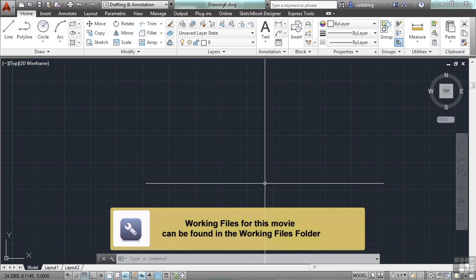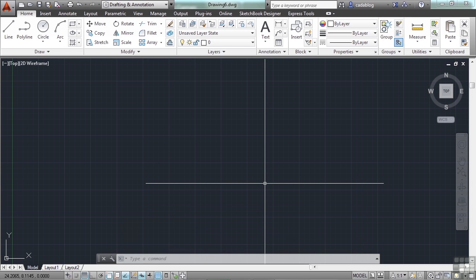When working with objects in AutoCAD, you will need to select items that are already there. Most drawings will require that you select something. There are many different ways to select objects and to make sure you are selecting the right one. When you're using an editing command, you will see a prompt on the command line that says Select Objects.